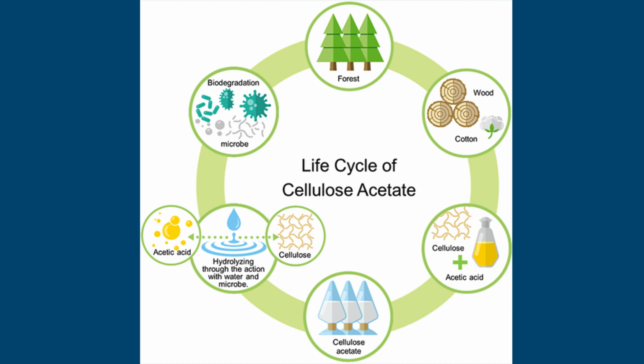In conclusion, cellulose acetate remains one of the most versatile and commercially important cellulose derivatives, combining renewable origins with excellent optical, mechanical, and processing characteristics. Through controlled acetylation, a family of materials, including cellulose diacetate, cellulose triacetate, cellulose acetate butyrate, and cellulose acetate propionate, has been developed to satisfy diverse industrial requirements.